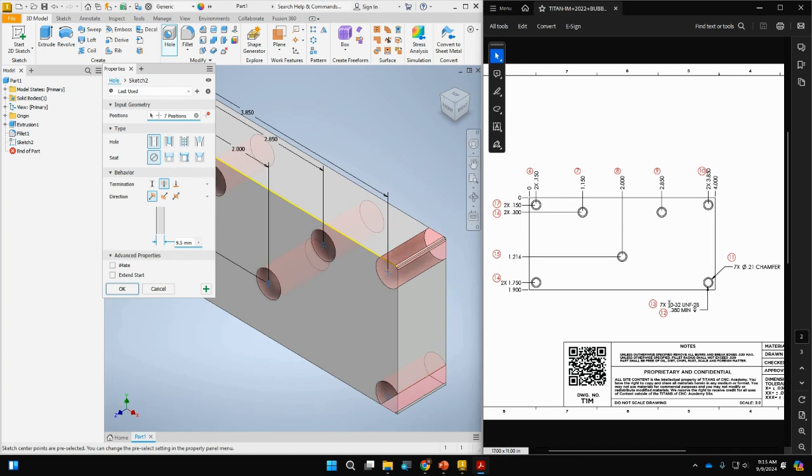It's a number 10. It's not a fraction, like a quarter of an inch. It does have a fraction to it. This is important because when we machine this, we have to drill a hole first, a size a little smaller than this. Then we go through and tap that hole, which adds the threading to it, right? In wood, we can make our own threads with our screws, but in metal we can't do that. So we have to create the threads for bolts or screws or whatever to go into.